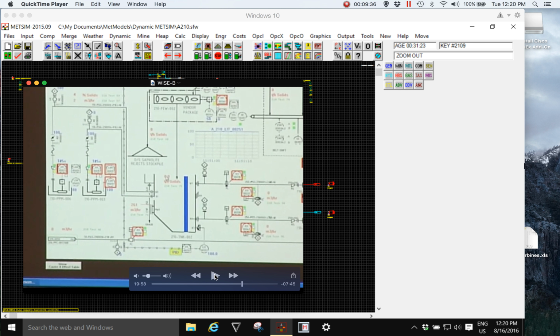Okay, I'm going to stop the demonstration video at this point. So the important thing here is we're seeing a live dynamic data connectivity between a METSIM model that is being started and controlled from a SCADA system. The information is being shared across to a walkthrough 3D games-like environment, and this is being achieved with an overriding program that we wrote using DLLs and using OPC connectivity.